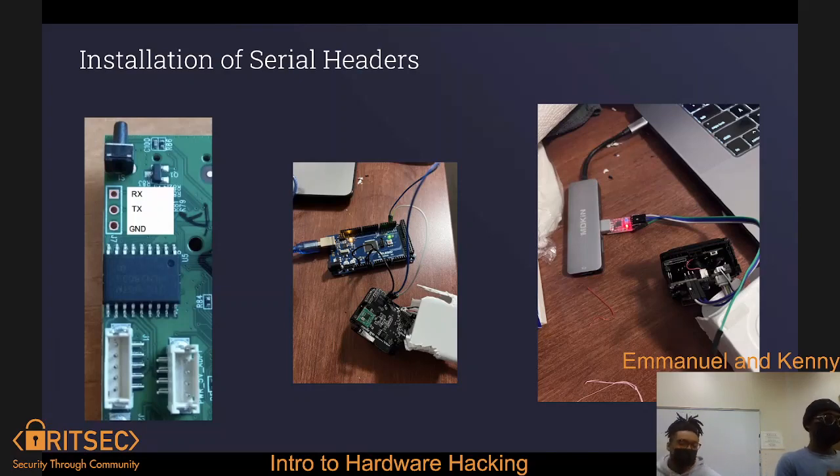At this point I didn't have a UART to USB adapter, the FTDI, which converts USB to serial. This little red device in the picture pretty much converts that UART information to my computer so I can easily see it and use my laptop as a debugger. Before I even found out about that, I thought I could use my Arduino to do that conversion. I saw a YouTube video and it seems like it worked, but not in my case. Nothing was working.